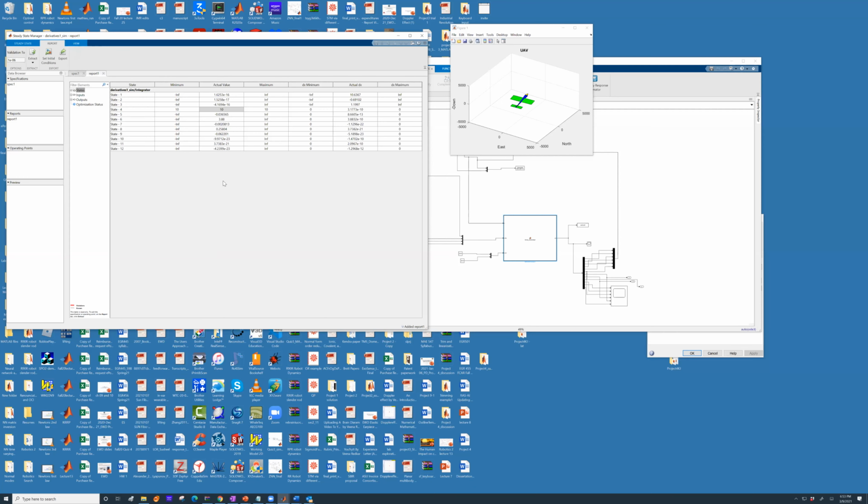Okay, this is the report. In certain cases, you will get some parameters as red, and those mean those parameters are outside the specifications. Next thing is you can set initial conditions. Everybody see this set initial condition button here? Click on set initial condition, and then you will see that exported report 1 to Matlab workspace, which is used to initialize derivatives 1_sim.